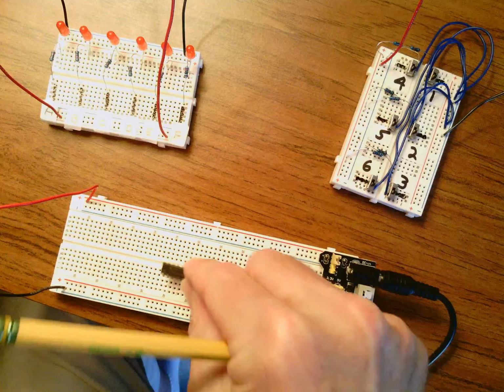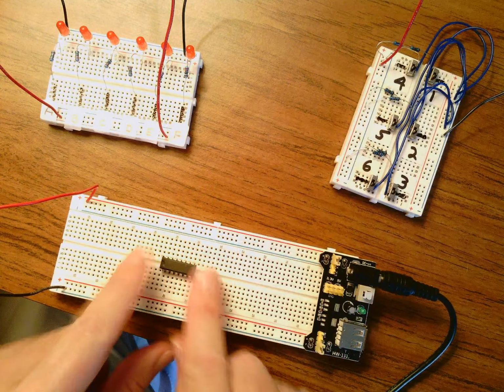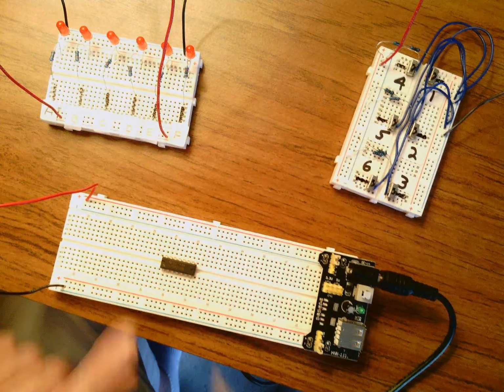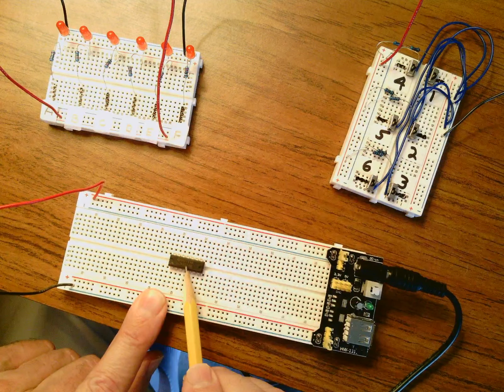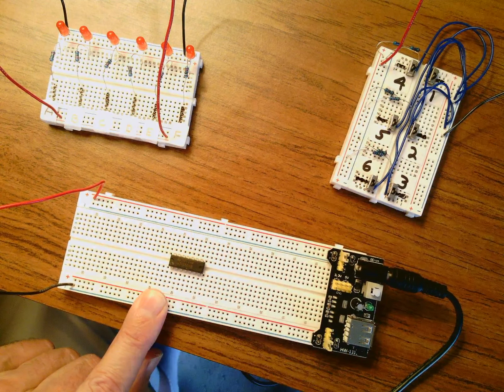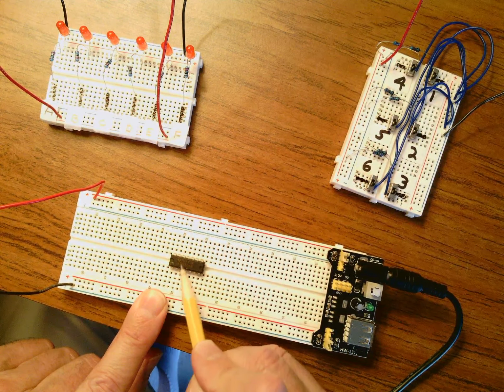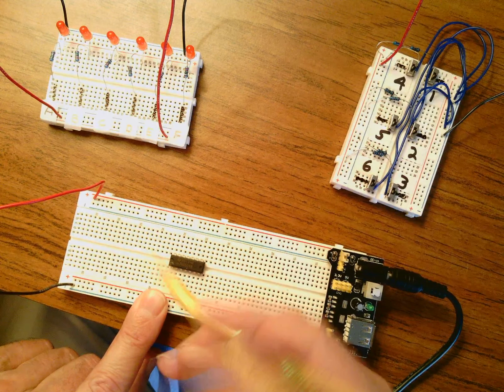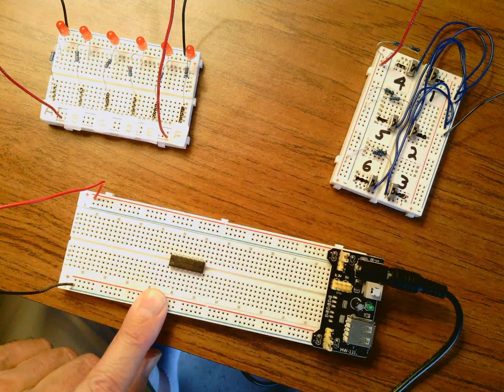Always insert those chips very carefully in the main board like that. Make sure your notch is always pointing to the left on every chip you put in here. On some of these labs, you might have 5 chips across there. If you put these in backwards, you'll draw excessive current, you'll blow up your power supply. You have to be real careful with that. Make sure you insert these chips, you identify the notch, pin 1 and the notch always point to the left.